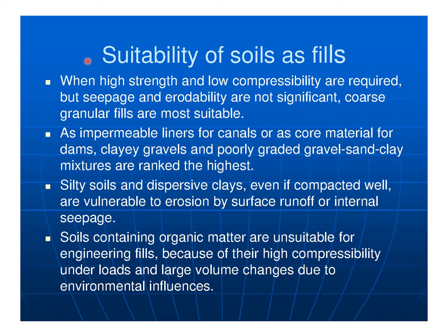Suitability of soils as fills. When high strength and low compressibility are required, but seepage and erodibility are not significant, coarse granular fills are most suitable. As impermeable liner for canals or as core material for dams, clay gravel and poorly graded gravel sand clay mixtures are ranked the highest. Silty soils and dispersive soils, clays, even if compacted well, are vulnerable to erosion by surface runoff or internal seepage.